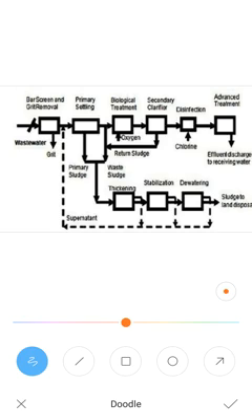In this preliminary process, it is carried out with three units: screening, grit chamber, and skimming tanks. What is screening? Screening is for removing the floating materials. The second one, the grit chamber, is for the removal of grit and sand particles, and the third one, skimming tanks, is for removing the oil and grease particles present in the sewage.